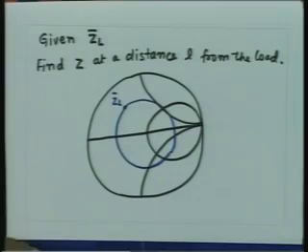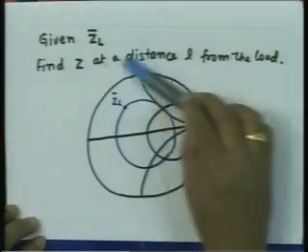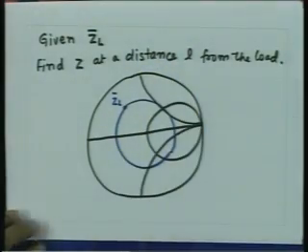Okay. Now, as we move on the transmission line, the angle changes by 2 beta L in the clockwise direction. Normally, for the standard Smith chart, instead of marking the angles on the periphery, the distance is directly marked on the periphery of the Smith chart. How do we do that?